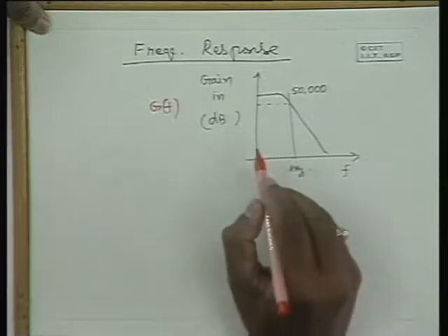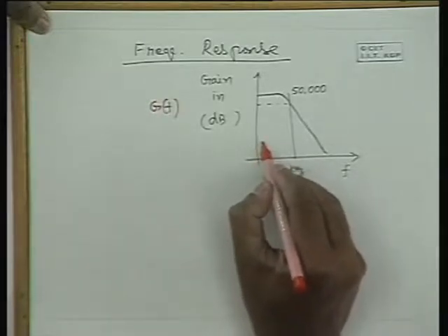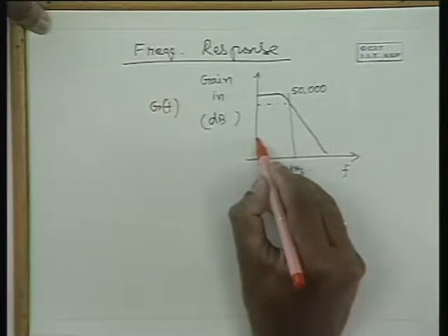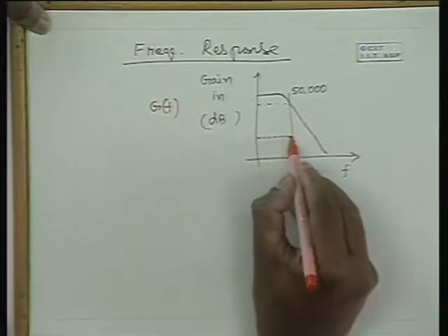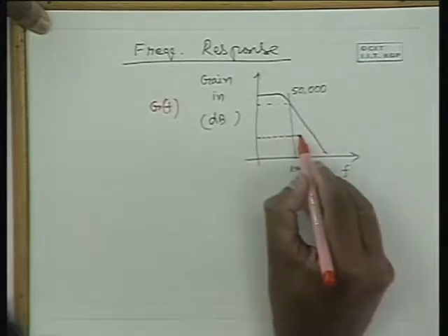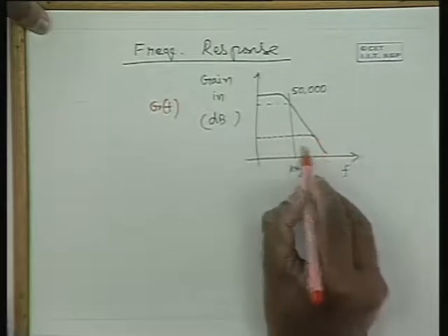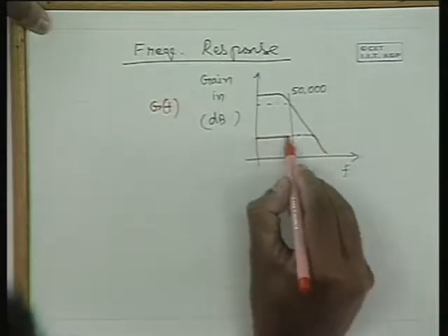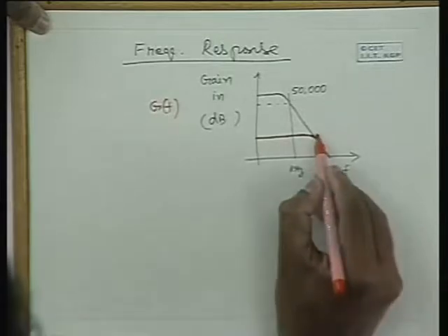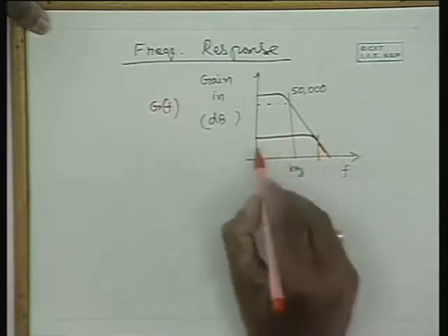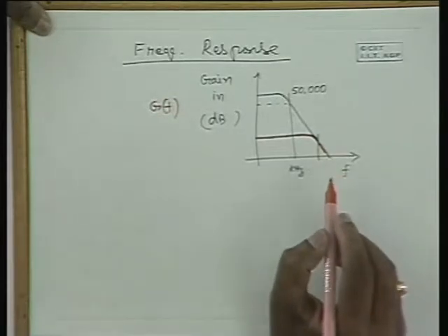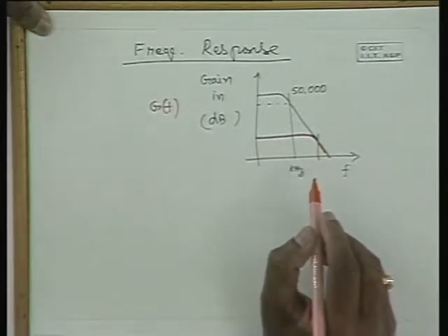Now through a feedback arrangement we may use it as an amplifier with gain equal to say minus 100 of that order, in which case the frequency response of the amplifier may be like this. The cutoff frequency of the amplifier goes up by the factor 1 plus A beta.